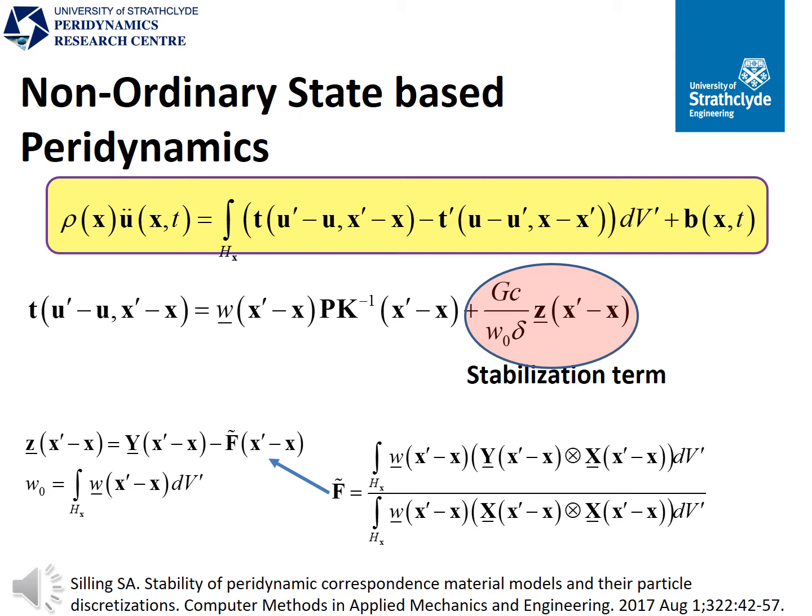To overcome this problem, Dr. Silling introduced a stabilization term, which is included in the peridynamic force expression as shown in the peridynamic force definition in the slide. Here, C is the difference between the deformation state and the average deformation gradient calculated from peridynamics, and W0 is related to the influence function. G is a constant parameter.